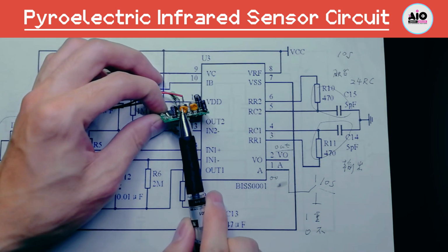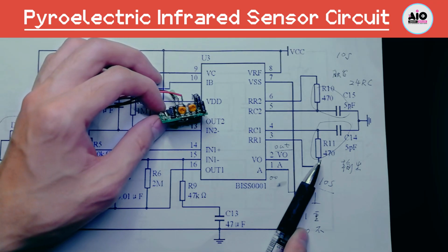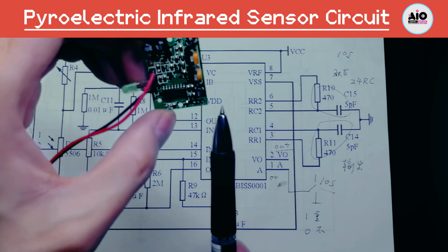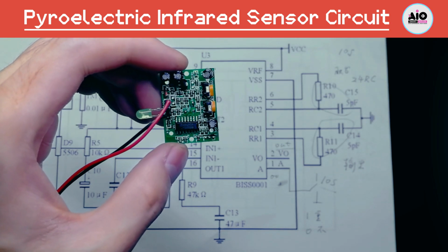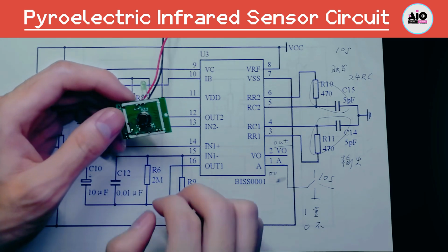The surface-mount package on the back of the circuit is the chip, BISS0001. In the middle part of the circuit board, this metal package is the pyroelectric infrared sensor. There are two adjustable resistors here. The adjustable resistors are used to adjust the delay.